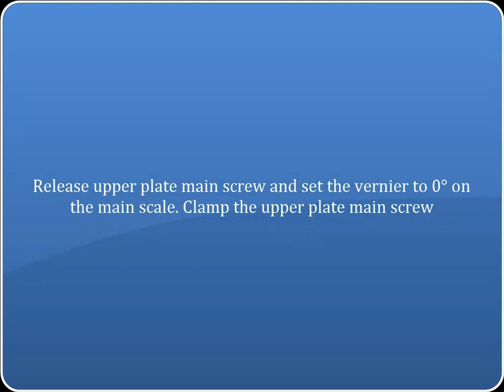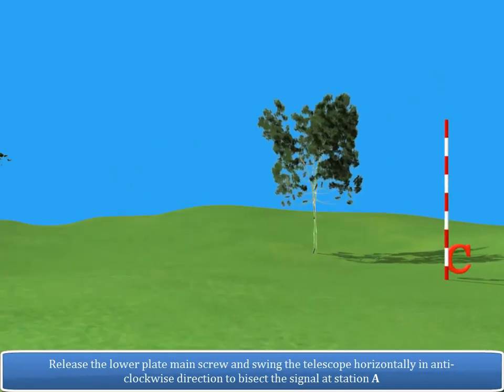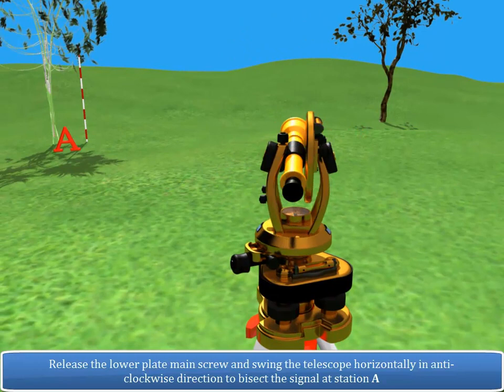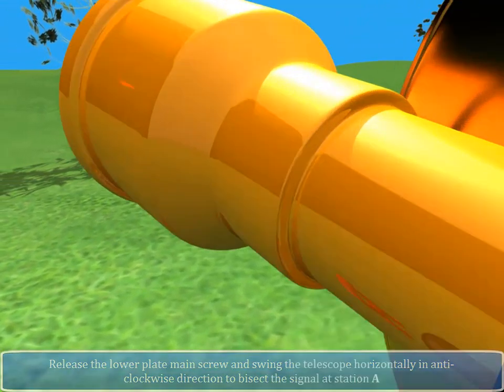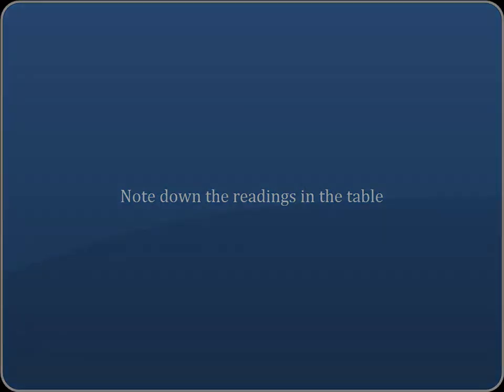Release the upper plate main screw and set the vernier to 0 degrees on the main scale. Clamp the upper plate main screw. Release the lower plate main screw and swing the telescope horizontally in an anti-clockwise direction to bisect the signal at station A. Tighten the lower clamp screw and use the lower plate tangent screw for exact bisection of station A. Note down the readings in the table.